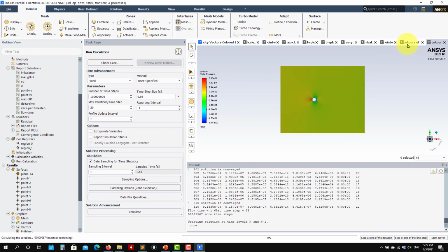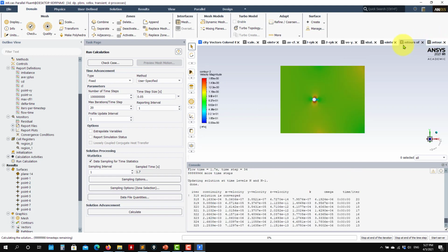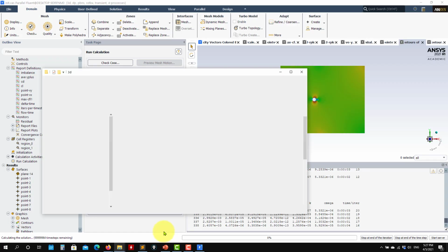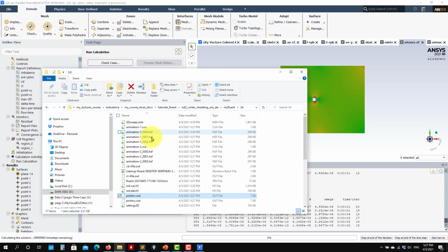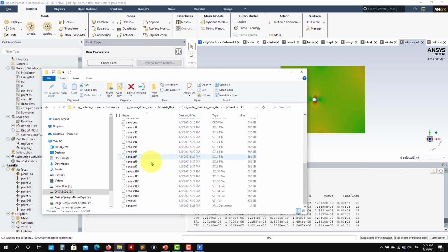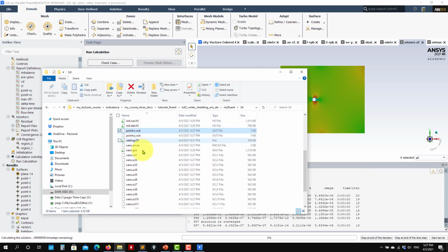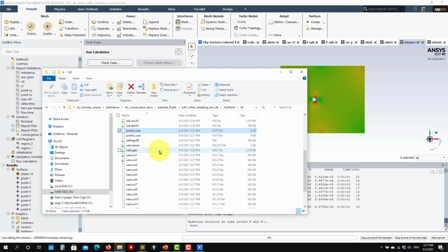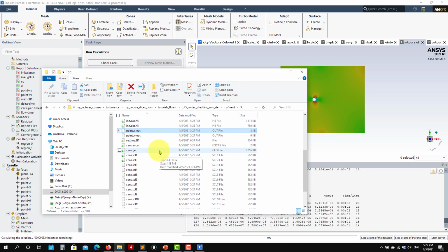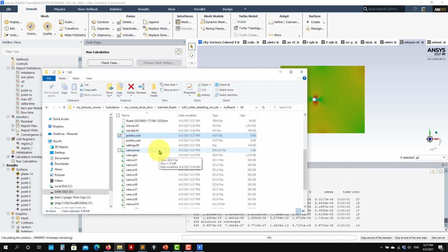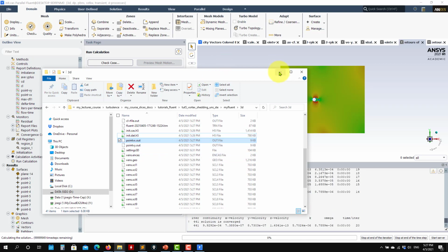And here you have the plots of the evolution of that. In this case, I'm saving in Fluent proprietary format, this one, HSA, and then you can animate it. But also see that you are saving these files here. These files correspond to Ensight. Ensight comes with your installation, and I will show you how to do that.